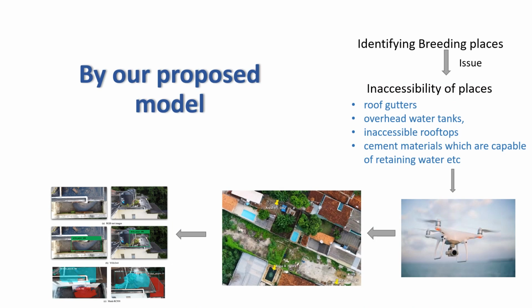At the initial stage of the research, a dataset of water-retaining sources, which have uneven boundaries of water, was created using images captured from a drone camera. The quality of the captured images depends on the sensor capacity of the drone camera and the ground sampling distance. We have considered a ground sampling distance of 7 cm or larger, which is sufficient to identify the objects clearly using the classification system. The custom-built dataset contains a total of 600 images.